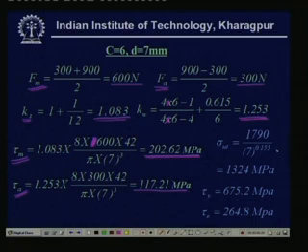Now, the question comes about what will be the material of the spring and what should be the corresponding strength values. We have seen that in the Soderberg criteria we require the material strengths like tau yield point and tau endurance limit, and both of these can be derived either from the database, from the design handbooks, or we can use the relationships we learned during the spring design.